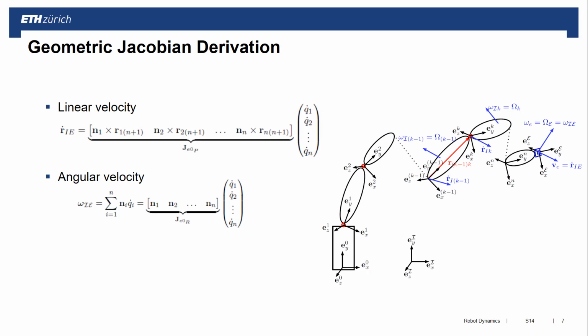Now in the exam, we're going to look at a kinematic chain like this. As you can see from the exercises we're doing here in the quiz session, but also in the exercise session, this robot cannot be arbitrarily complex, because otherwise you would spend the 2 hours just to do the simple math. We're not going to check whether you can multiply cosine and sine functions. What we will check probably is, for example, we give you certain aspects of these Jacobians. You have to identify other ones. Maybe we give you a Jacobian at a certain point, then we want to know it at another point. Things like this to figure out whether you understood the problem or not.